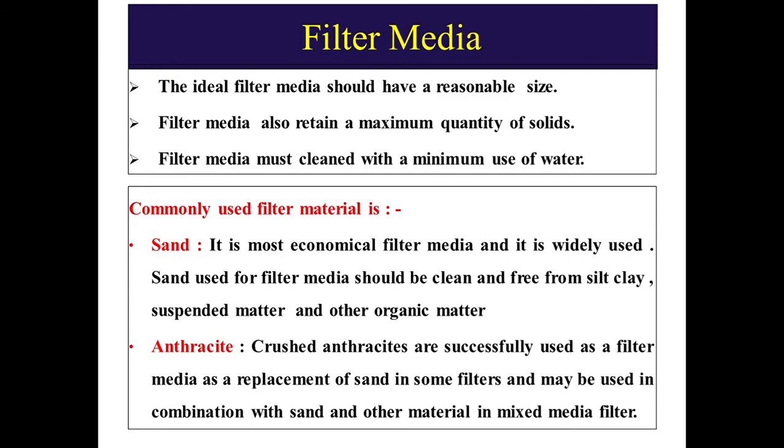Commonly used filter media is sand. Sand is the most economical filter media and it is widely used. Sand used for the filter media should be clean and free from silt and clay. It is also free from suspended matters and organic matters.